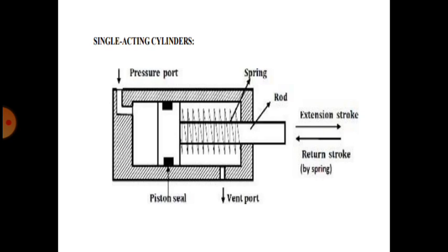In a hydraulic system, pumps transmit the fluid in the lines or system by continuous pumping action, and an increase in the fluid pressure is caused by resistance to the load. The mechanical energy input through a prime mover is converted into fluid power by the pumps. The fluid power in turn is converted back into mechanical energy by the hydraulic actuators and motors. So already we have shown circuit diagrams using linear actuators and motors.